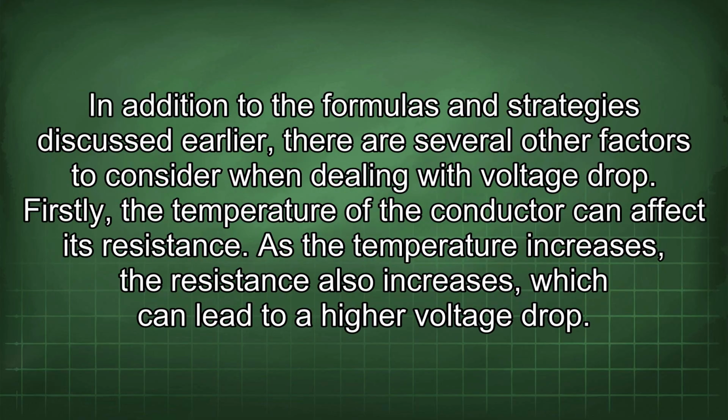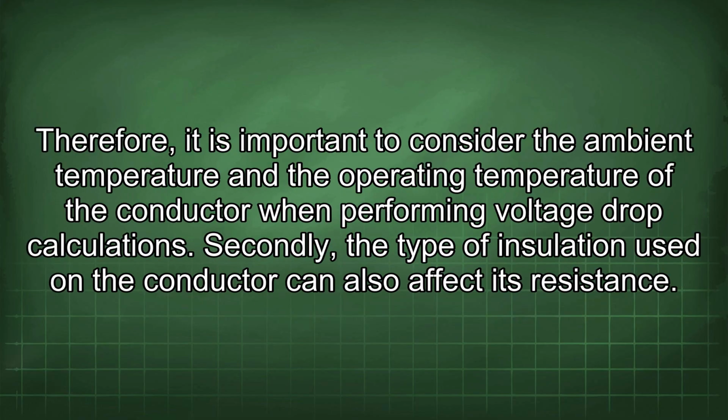In addition to the formulas and strategies discussed earlier, there are several other factors to consider when dealing with voltage drop. Firstly, the temperature of the conductor can affect its resistance. As the temperature increases, the resistance also increases, which can lead to a higher voltage drop. Therefore, it is important to consider the ambient temperature and the operating temperature of the conductor when performing voltage drop calculations.